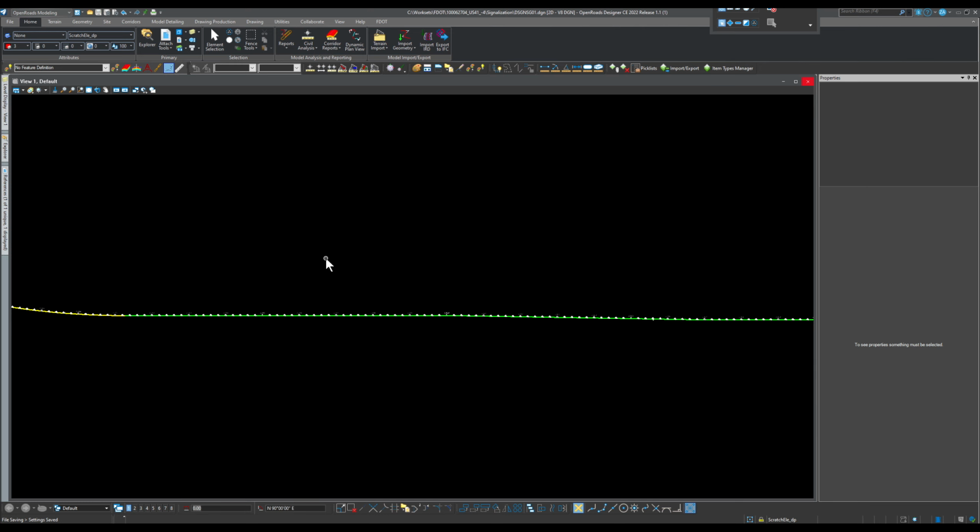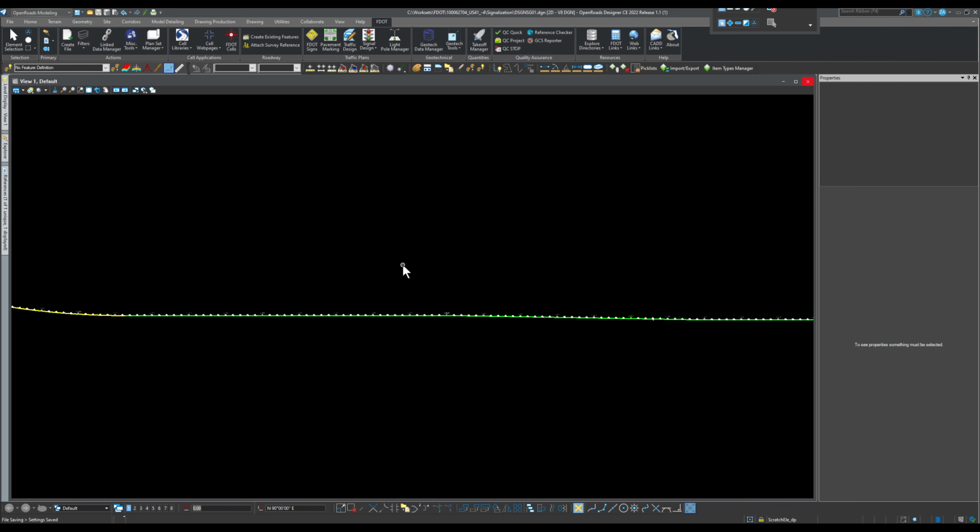So what we're gonna do now is, first things first, let's just do FDOT before I run takeoff manager. So what I'm gonna show you in this video, like I said, is another way to do quantities, because DOT already provided their way of doing it, which is using these tools. From here you can get the signals. From here you get some of the conduits and some of the lighting. From here you get pavement marking, and from here you get the signs.